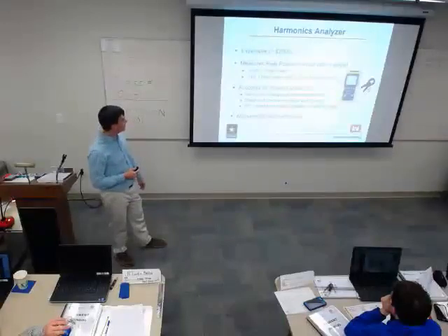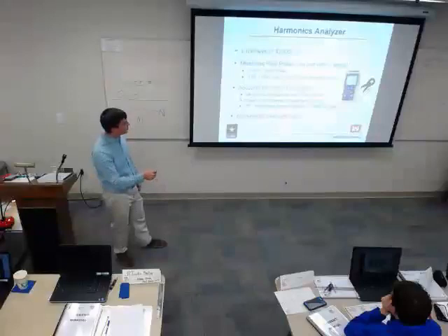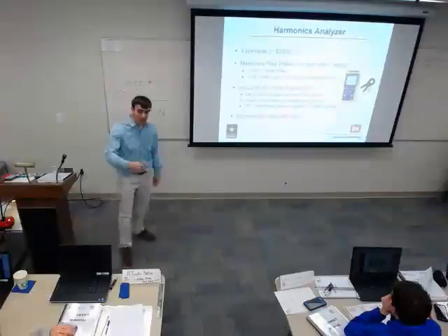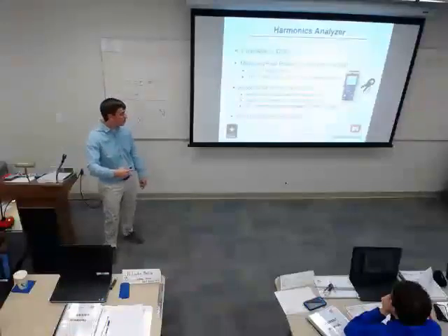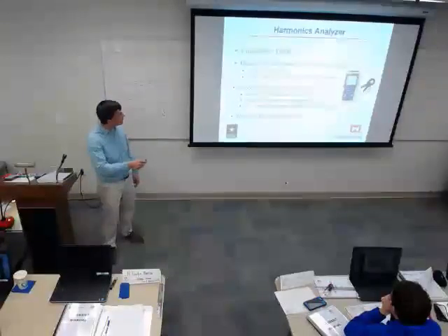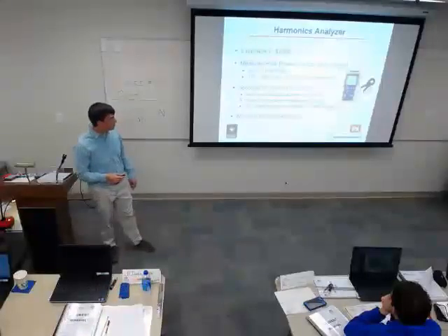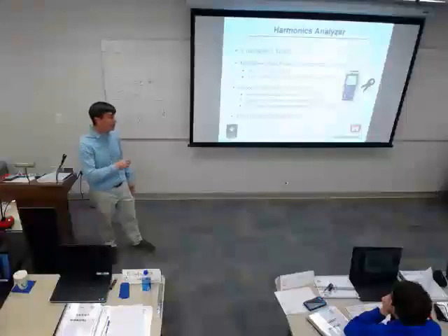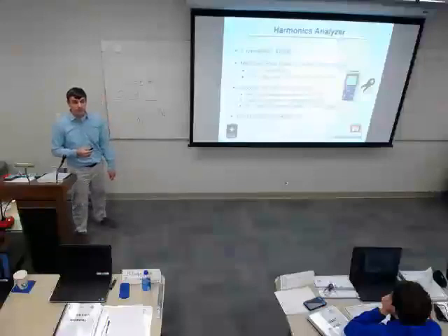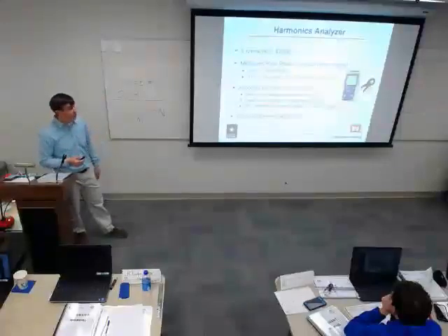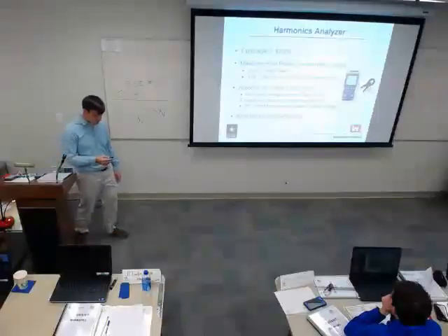Talked about the harmonics analyzer, and again, if you're needing some instrument where you have to know exactly what the power is, you have to use something like this, or they make another instrument as well. But you can see, they're pretty expensive. This line's pretty old, they're probably more than that. But for capacity testing for big pieces of equipment, you might have to pull out one of these, because your power factor is generally going to be like 0.8 or 0.9. So you might have that much of a difference in your reading if you're not using a harmonics analyzer.